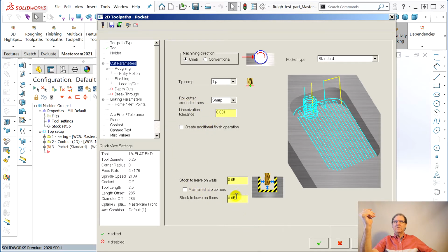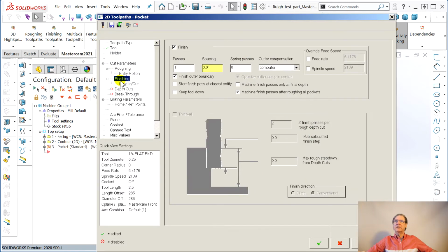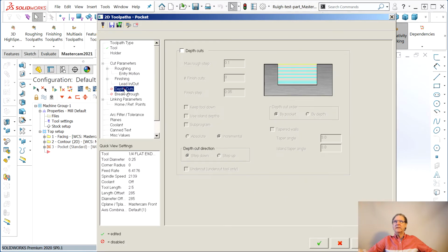See stock, always wants to leave stock. Now don't leave any stock on the bottom. This is a roughing, so I guess you do 0 stock on the bottom. Finishing, I guess that's okay. Depth of cuts, let me think. Oh yeah, it's a deep pocket. We want to go 125 down. So I think that's all going to...